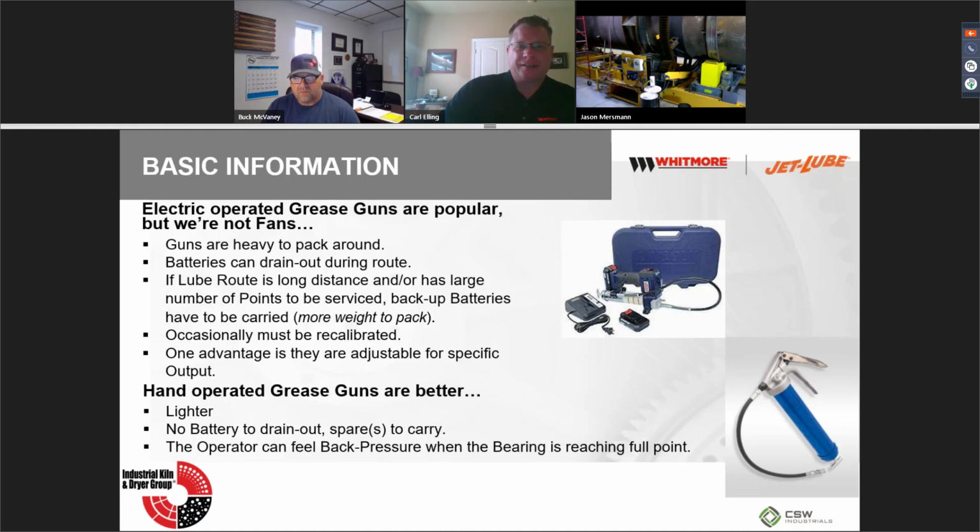I've talked to a couple of maintenance guys that had these, and they've got their grease routes, of course. And I asked the one guy, well, how many shots do you put in this thing? Oh, I go until I hear the difference in the whine of the motor. And then you look at the bearing that he's greasing, and it's got grease coming out of the seal, and it's all over the place. So again, over greasing, it's just a matter of educating. That particular bearing, after we went through the exercise, only needed to be greased once every 4 months, and he was doing this every week. So this is what we're going through.